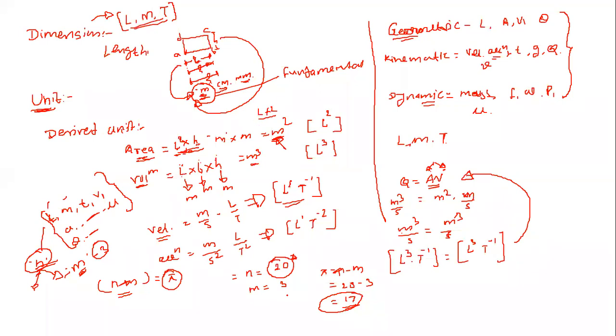This is the basic of Buckingham's pi theorem. Okay, and then while forming those 17 pi terms out of the available 20 variables involved in that particular phenomenon of the crashing of the aircraft, we don't know how many there are, but we have considered 20 physical parameters, and out of that, 3 fundamental dimensions are there. Means we will be able to group those 20 parameters into 17 non-dimensional groups, non-dimensional parameters we can say, that is pi 1 to pi 17. So I would like to write here: the number of pi terms that we will be able to form are pi 1 to pi 17.